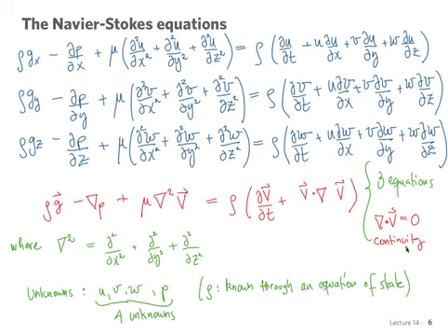The assumptions of this are that we have incompressible flow and Newtonian fluid. So these Navier Stokes equations do not apply to strange fluids like we saw in the beginning of the course, where you had shear thinning or shear thickening situations. Then you have to do some sort of other manipulations to the stress terms, and you might get a similar equation, but it's not going to be the Navier Stokes equations as we've written them down here. And so the basic quantities that appear in the Navier Stokes equations are weight, pressures, all the viscous forces, and the acceleration, local and convective acceleration.